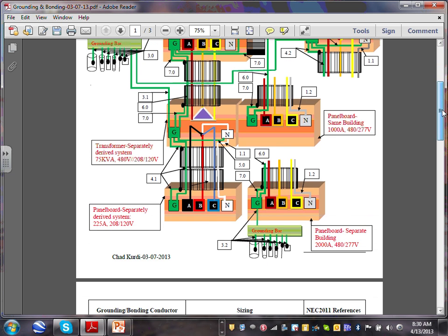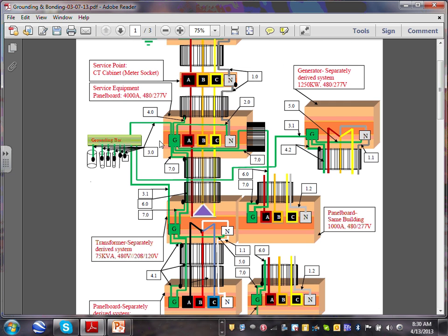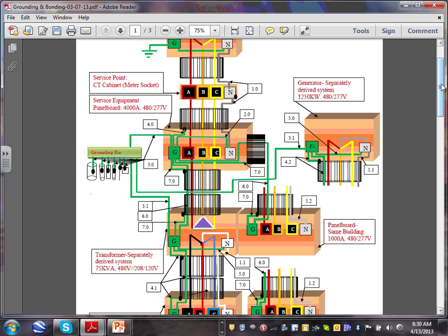So that's basically what this sheet is supposed to do: taking a service panel and 3 feeders out of it. One feeds a separate building, one feeds a separate panel in the same building, and one feeds a separately derived transformer that feeds the receptacle panel in the same building. And we have a generator that we need to tie to the system, and we need to do grounding and bonding for that system. Any comments, guys, about the big picture? Everybody can see what the...